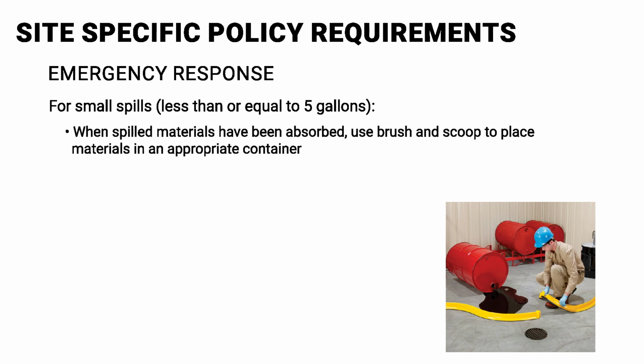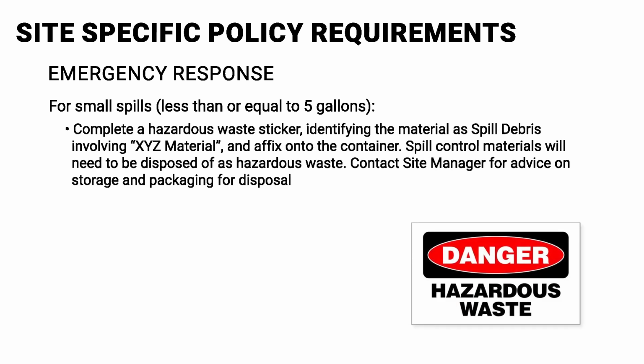When spilled materials have been absorbed, use brush and scoop to place materials in an appropriate container. Complete a hazardous waste sticker identifying the material as spill debris involving XYZ material and affix onto the container. Spill control materials will need to be disposed of as hazardous waste. Contact site manager for advice on storage and packaging for disposal.